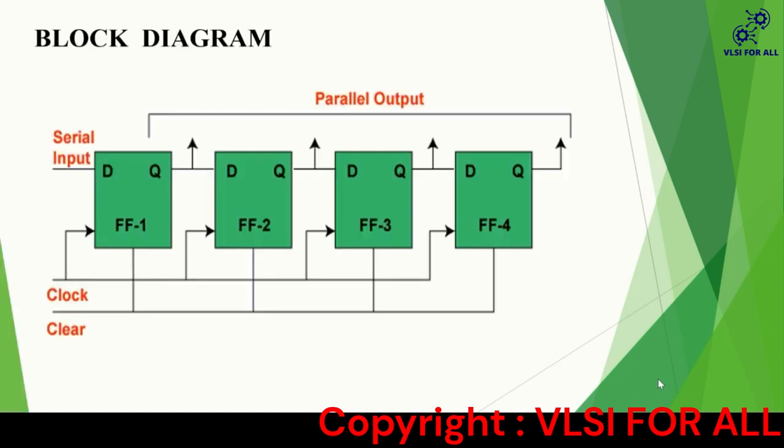Here, in the serial input and parallel output shift register, the data is passed serially to the flip-flops and outputs are fetched in a parallel manner. The data is passed bit by bit in the register and the output remains disabled until the data is passed to the data input. When the data is passed to the register, the outputs are enabled and the flip-flops contain their values.